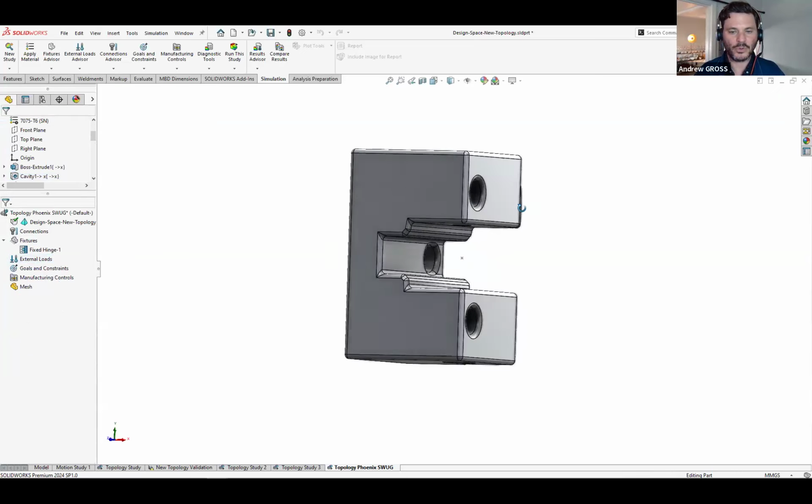So if I right-click external loads, I can put something called a remote load. I know my remote load is going to attach to the same place that the steering ball actually connected, with an axle going down inside of it. I know it's going to connect to the same location, but I want it to be applied right in the dead center. Basically, that's where the nucleation of the force is going to be, right in the dead center of these two holes.